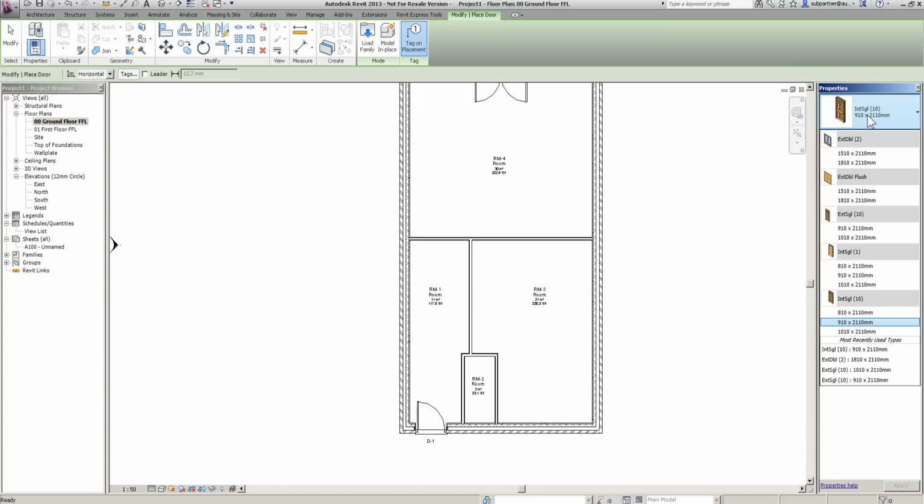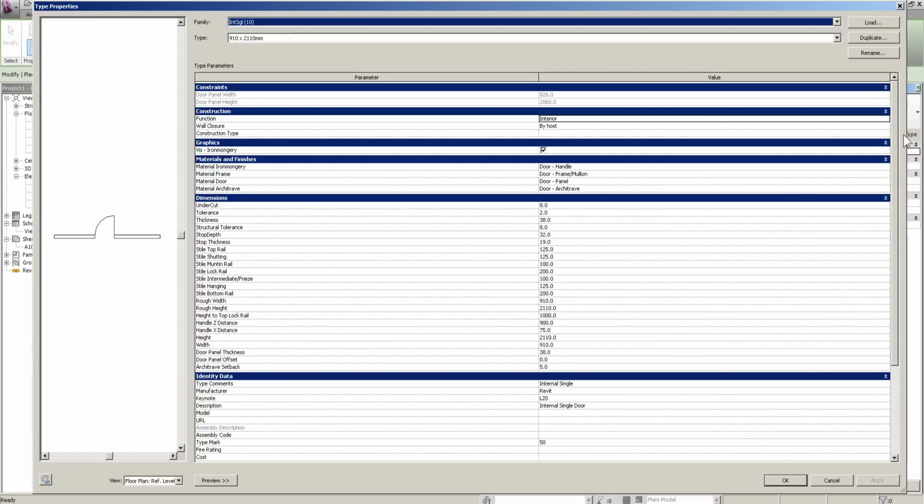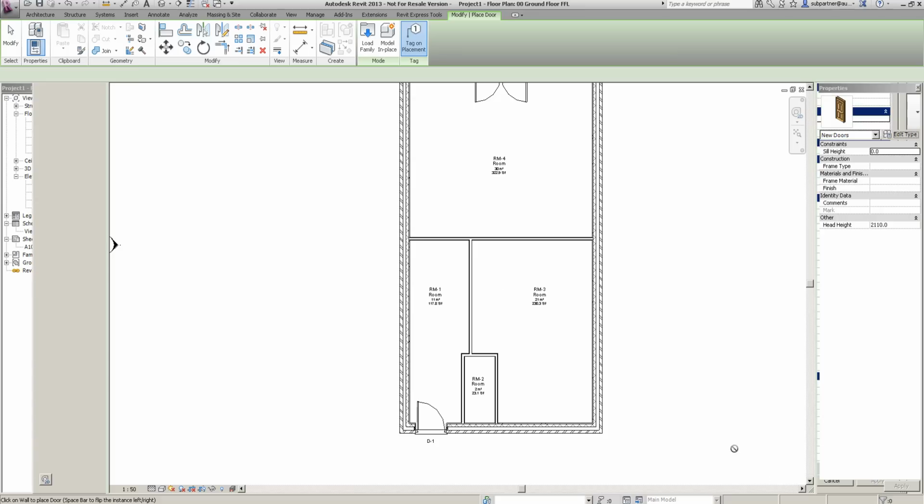Okay, there we go. Now, I'm going to put some 910 doors in. These work quite nice with the metric door openings, okay, because if I go edit style, edit type up here, if we look at the 910, this is a structural opening. It gives you a door panel of 826, which obviously, as people in construction know, that's a metric door. I quite like that. It's got the tolerances outside of the frame, in the frame between the panels, and then obviously the frame sizes and all of that collaboration, so it works quite nice.